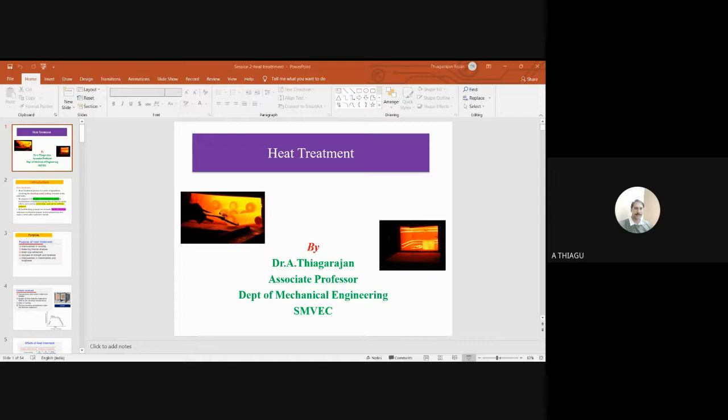So these are the major considerations for the stress relief material. Again, the temperature we have to fix for stress relief annealing is 550 to 650 degrees centigrade, which is normally preferred. Stress relief is also called recovery. Please note down the term: stress relief is also known as the recovery process.